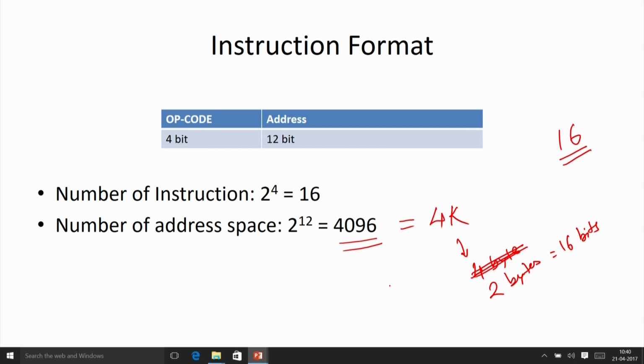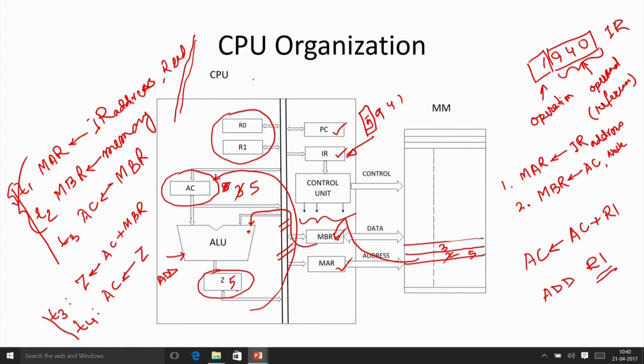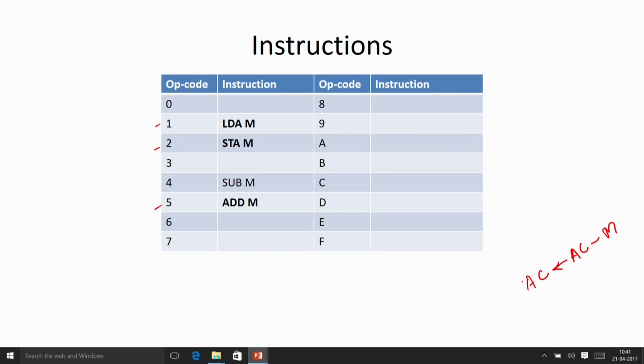If you see the organization, we have some general purpose registers, R0, R1 like that, 8 different registers. The contents of a register can be taken out and put into the accumulator with the help of this instruction 9000. It refers to register 0, and the opcode says take this information and bring it to the accumulator. Like that, we can have the effect of those instructions.